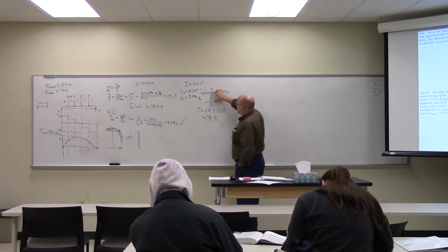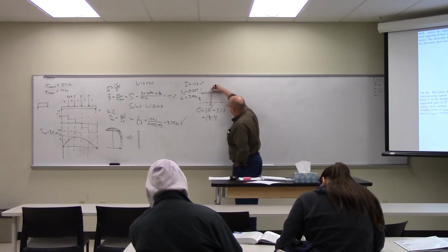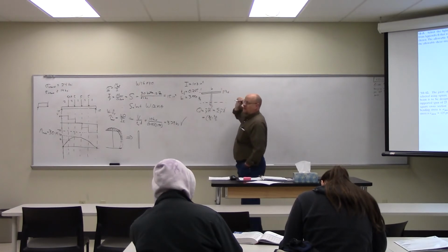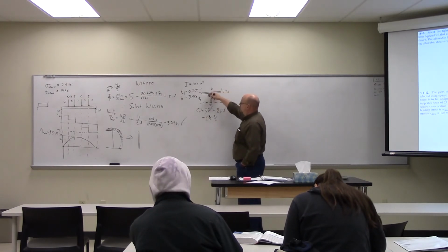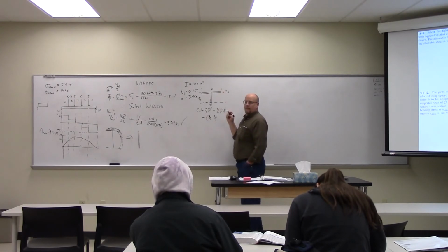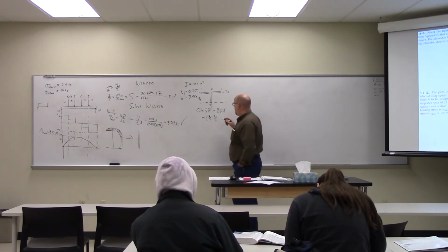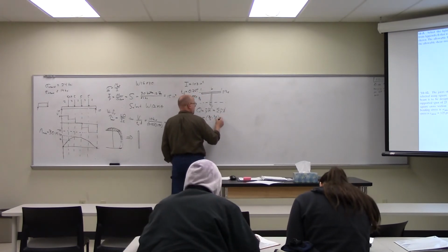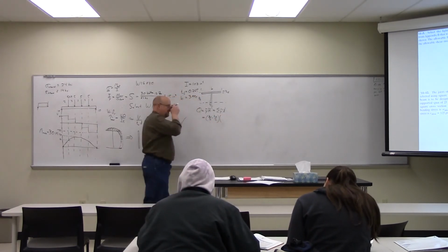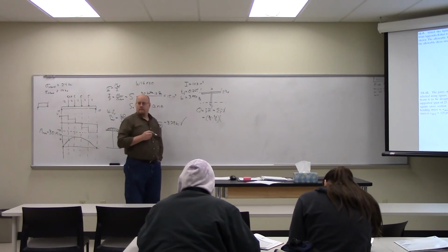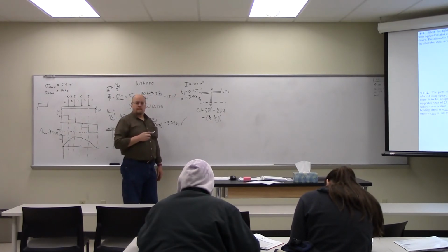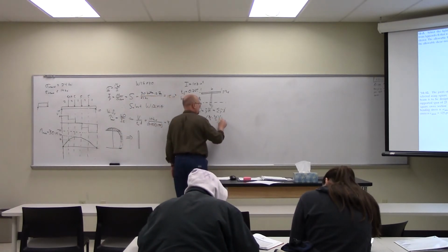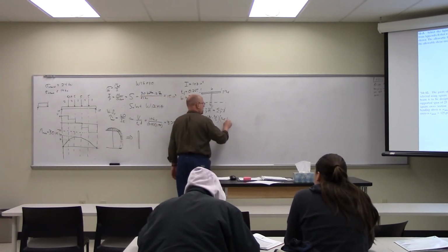Right? Is D the centroid of that piece? D is the overall height. So it's D over 2 minus TF over 2. Gotcha. We'll plug those numbers in a second. What's the area? TF times B.